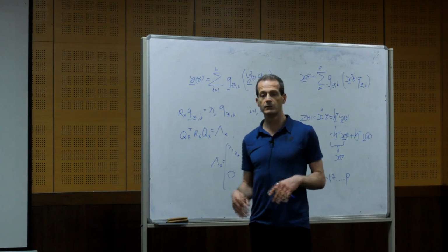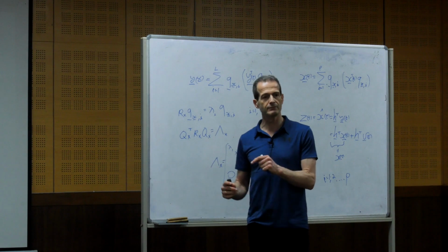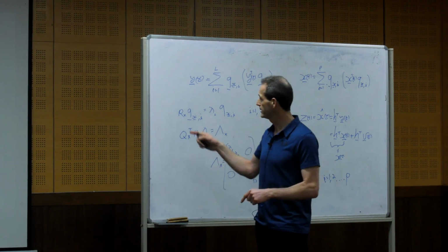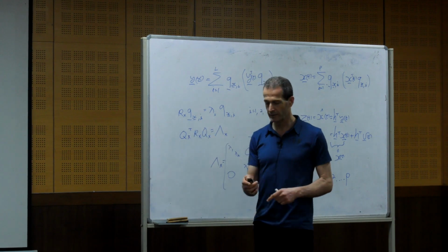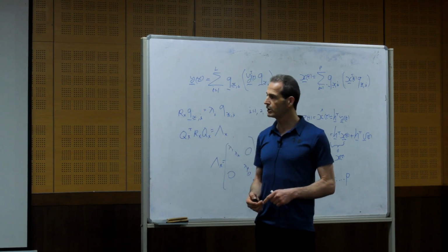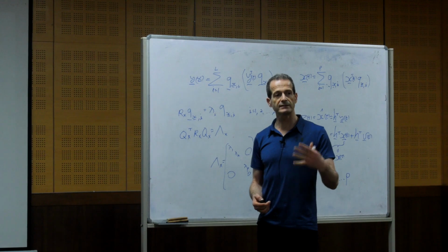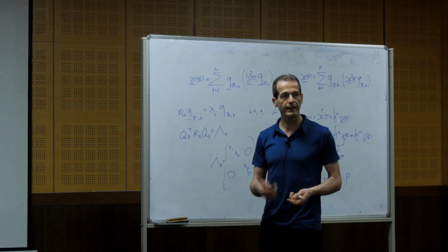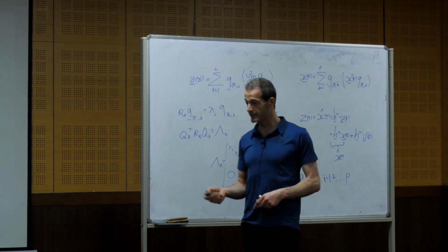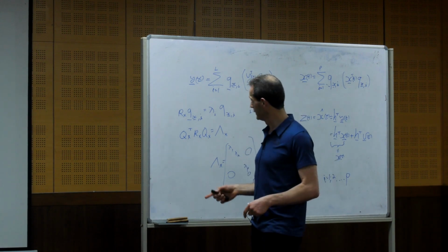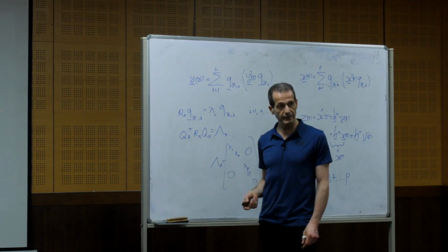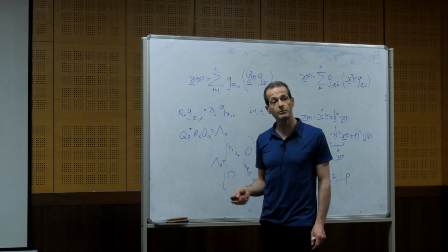Makes sense. Because with the Fourier transform, I don't need to change it. I don't need to estimate Rx in order to find eigenvectors. And also, I have a fast algorithm, the FFT, to do it on that window, of order N log N. So the computational complexity will be lower, whereas finding the eigenvectors of a matrix is high computational complexity.